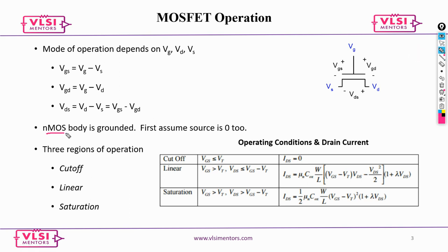So it is basically NMOS body is grounded. And what about PMOS? What if it is a PMOS? We tie it to power, sir. We tie it to VDD.